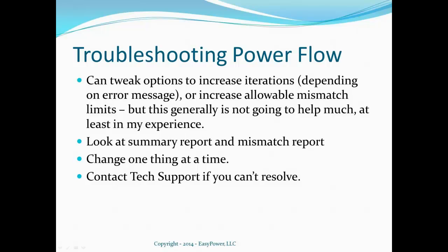The utility doesn't necessarily like that, but if you are a merchant plant or a cogen facility, you basically want to run maximum kW all the time, if you're assuming you're getting paid for export. If you're not getting paid for export, you're only offsetting what you buy, then yeah, you might have to have a different model there for how you regulate your kW. Also, the turbine generators generally like to run at a constant power. They don't like swinging back and forth in load.